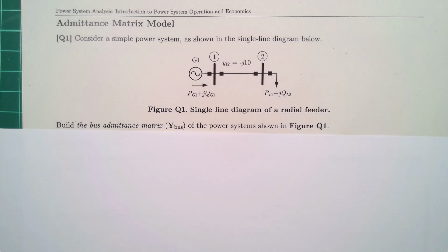As you must be aware, electrical power systems are very complex in terms of the size of the problem. Power systems tend to be very large, with large numbers of bus bars, transmission lines, and so on. For that reason, the best way to represent the power system is using matrices. And one of them, the admittance matrix model, is perhaps the most used model for power system representation.